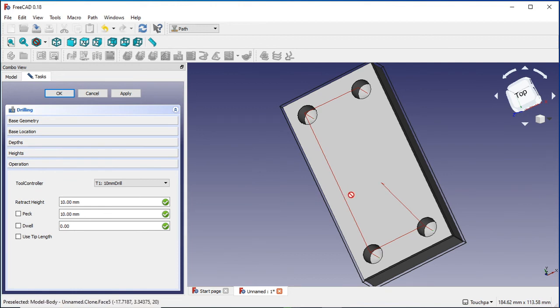If you didn't dwell in that hole, you would come down and back out, and the end part of that drill, the very bottom of that hole, may have only got half to a quarter of a revolution of drilling, meaning that you've got a burr in the bottom. So dwells are important if you want nice clean holes, especially if you're dealing with keeping an airtight seal or a liquid tight seal in there.